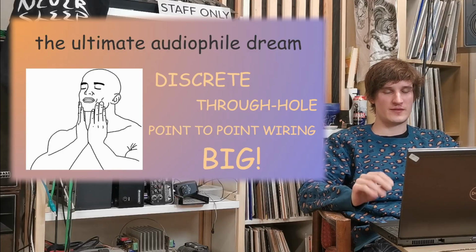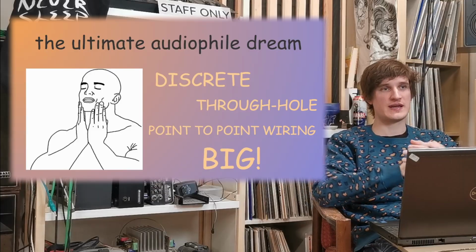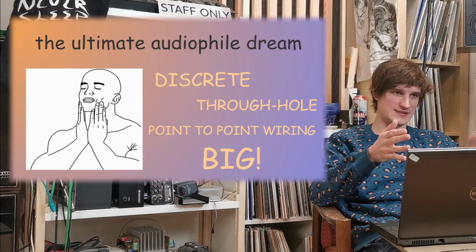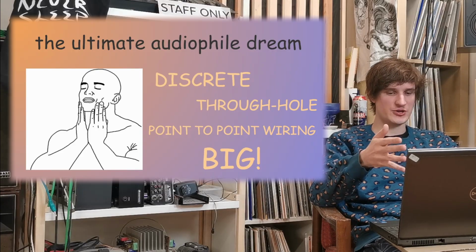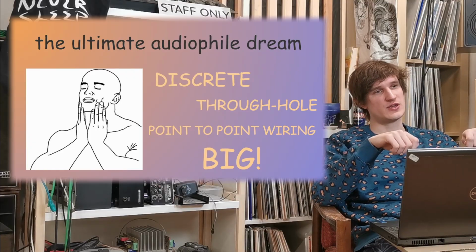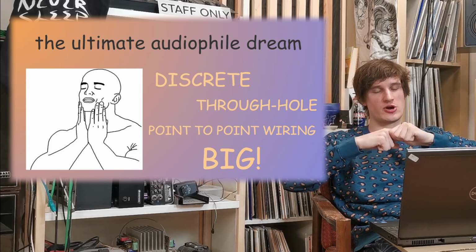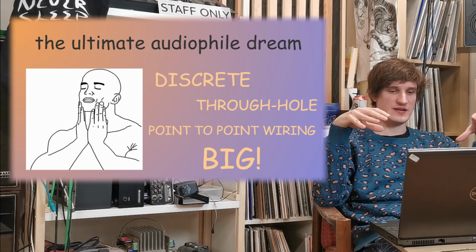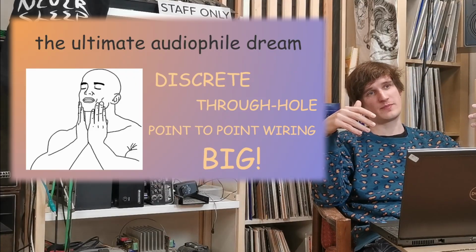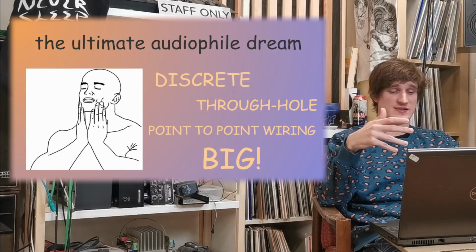Also, some people mention point-to-point wiring, and this is also an interesting topic, because it's not an accident that some gear has point-to-point wiring, especially tube amps, because thanks to this you can keep the connections reliable and strong. But mostly if we are speaking about benefits of point-to-point wiring, we speak more about larger power amps, not exactly preamplifiers and mixers.